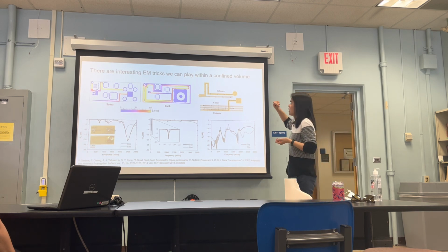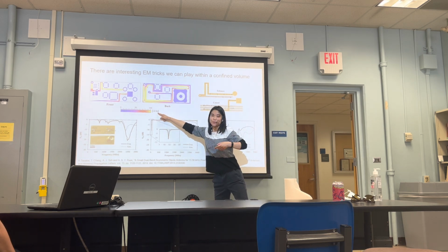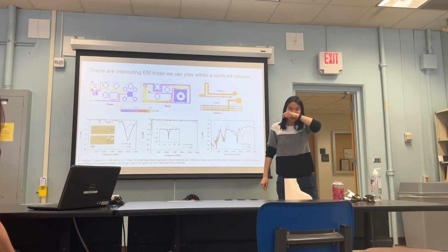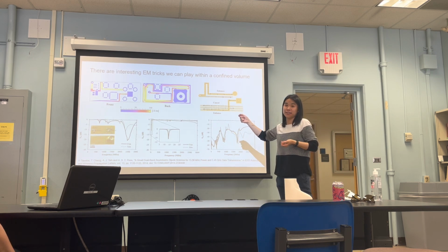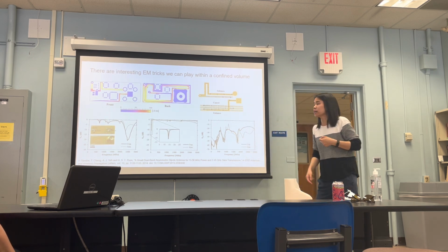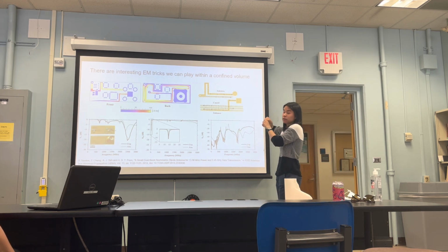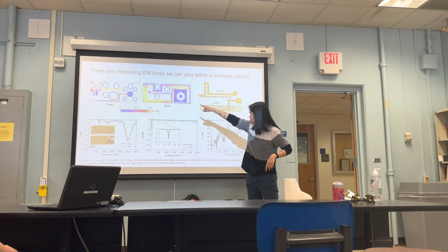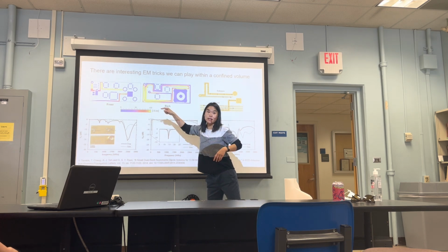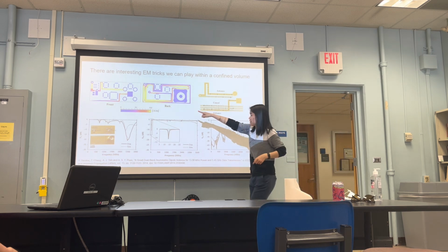And so what's being shown here, first of all, what is this parameter? Amps per meter? Does anyone learn that? Amps is current. Amps per meter is surface current. So it's a common way we look at antenna design. What's being shown here is areas where there's more current. All of this is metal. You see the front side, back side, there are these 2 small circles, those are vias, but this is one big loop, basically, with a little thing sticking out of it, which is that thing there.